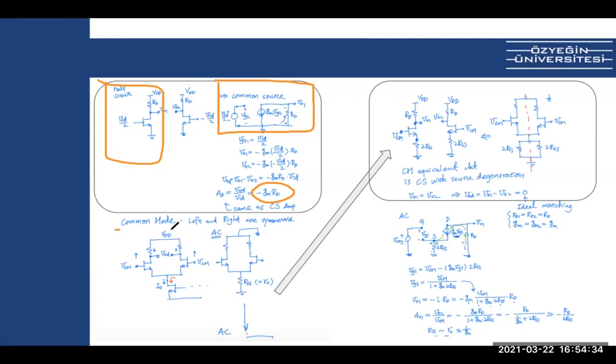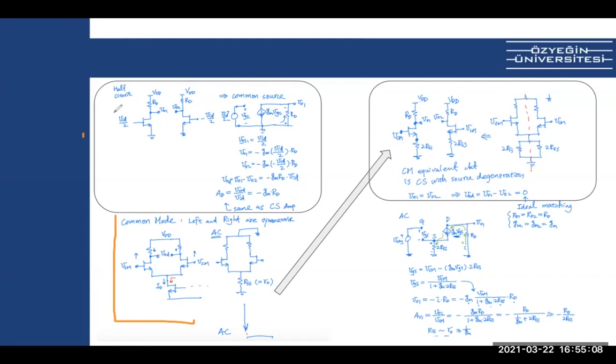How does it work in the common mode? Well, we have a current mirror here, right? It's coming from somewhere else. So this is actually a transistor. Because it's a transistor, it actually has a finite resistance, RSS. So when we do the RSS, and when we draw the common mode just like we draw the half circuits, we gotta draw the common mode. So looking at the common mode, this RSS, we can connect these two points because they are common mode. They have the same voltage.